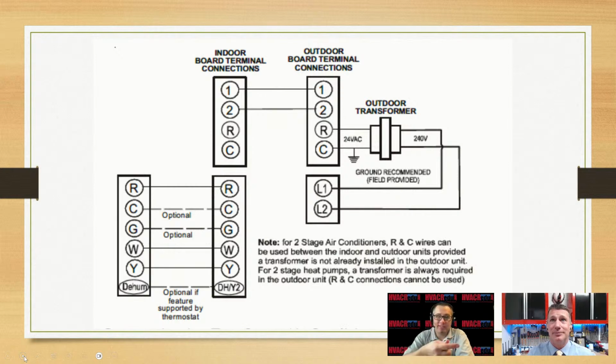I mean, on the T87 or thermostat side, what are you supposed to have? 24 volts. On the communicating side, whatever the parameters are by the manufacturer. That's right. So with theirs, typically, if it's a gas furnace, 2.2, 2.8 with a 0.6 volt DC bias between the two of them. And it shows you exactly on that outdoor unit where our 24 volt common is grounded to our chassis, to our grounded circuit. That is actually how we have our common reference from a ground of the outdoor unit, or common in the outdoor unit, back to the panel, and back to the indoor unit.